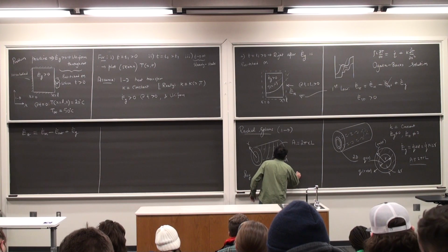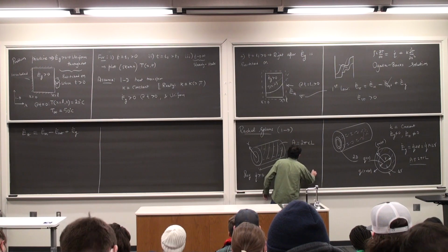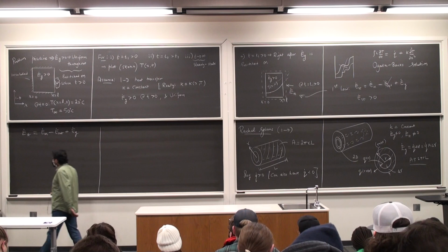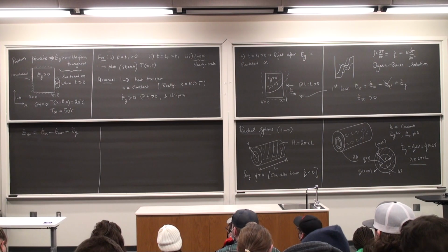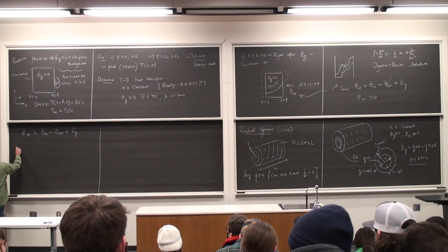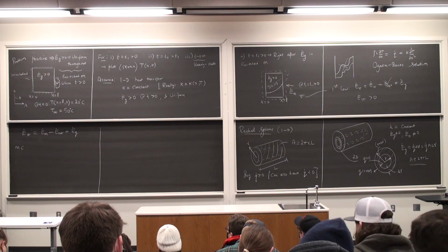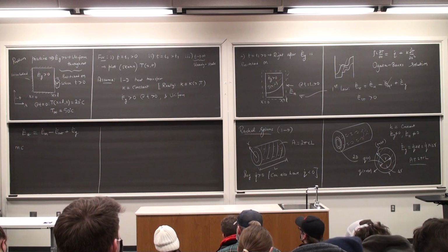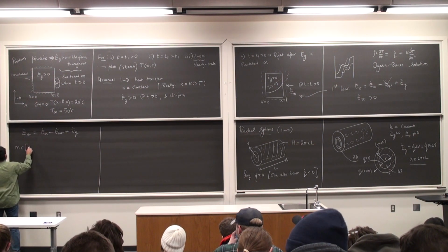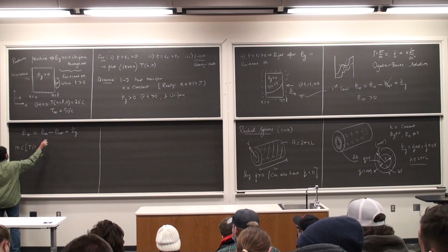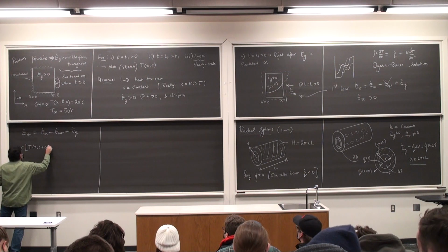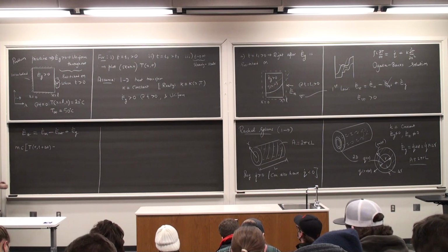Can also have Q dot less than 0, in which case it comes with a negative sign. Okay, so no big difference. E dot stored is mass times specific heat times the change in the temperature with respect to a reference temperature at two different time instances. So T at some R, function of R, T plus delta T minus T at R and T.